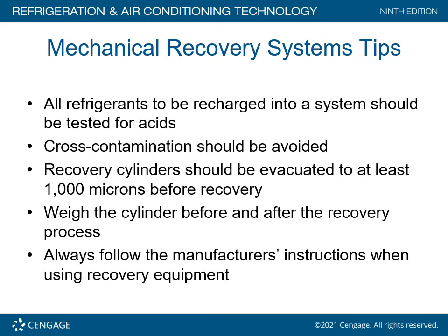Mechanical recovery system tips. All refrigerants to be recharged in a system should be tested for acids. Cross-contamination should be avoided. Recovery cylinders should be evacuated to at least 1,000 microns before recovery. Weigh the cylinder before and after the recovery process to determine how much refrigerant was recovered from that system. Always follow the manufacturer's instructions when using recovery equipment.